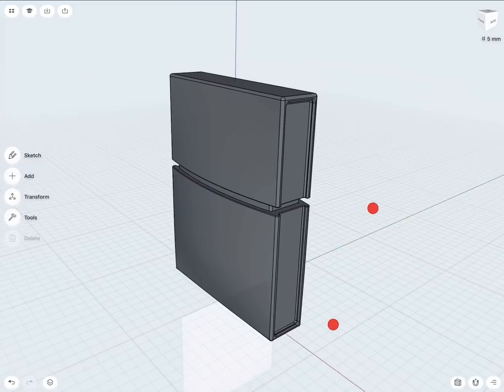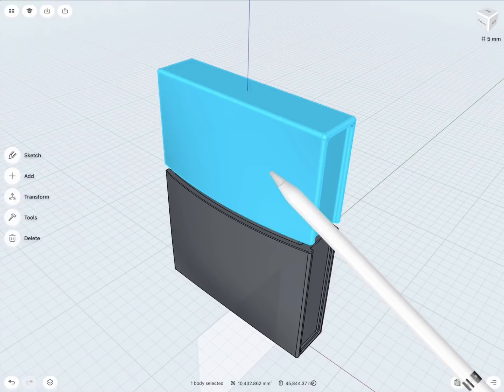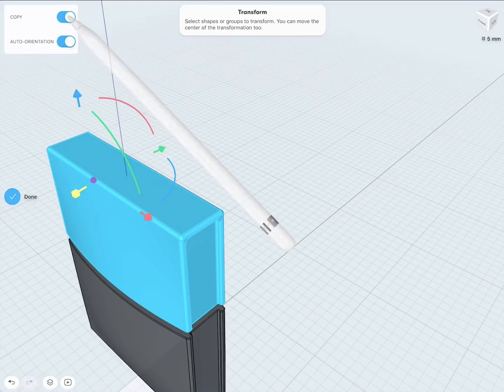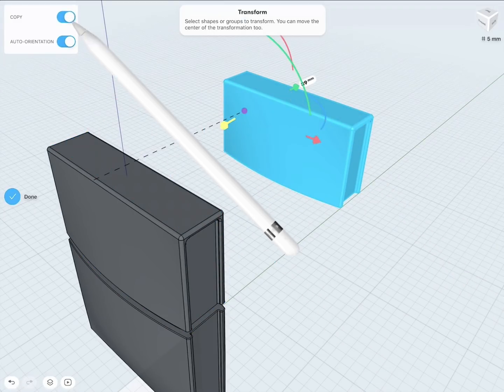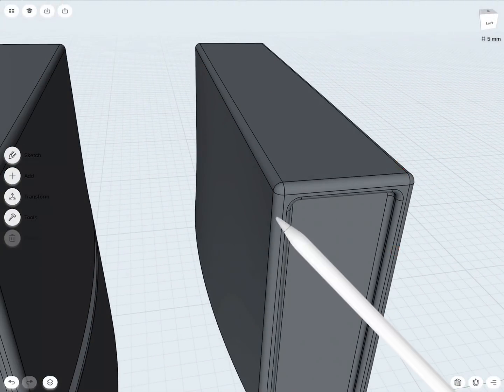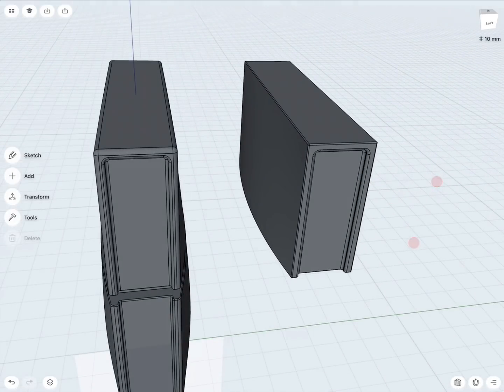Another thing, before I open this to question and answers, that's also really interesting with direct modeling versus parametric. Currently, you just see one object. In Fusion, I can't, or I kind of can, but I really shouldn't. I could select this and then make a copy there. Move this to somewhere else. So here I made myself a copy. And for example, in this copy, I simply say, well, these fillets I would like to be 2.5. Now I have two versions.